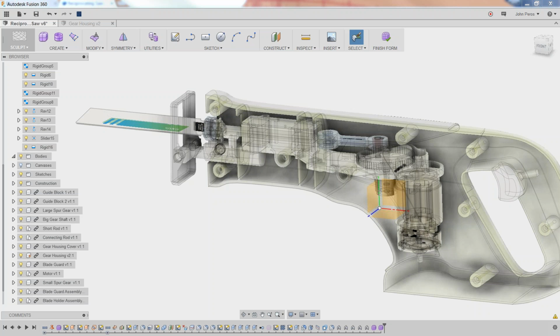With Fusion, you're going to be able to create completely closed, watertight surfaces using T-splines, and then move that immediately into the CAM environment in the same product, set up your toolpaths, and then if you change the T-spline model, your toolpaths will automatically update, so you won't have to reset anything up from a CNC perspective. That to me is probably the most exciting thing for you in that particular realm. Cool. I hope that helps.